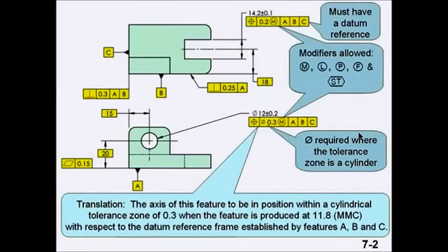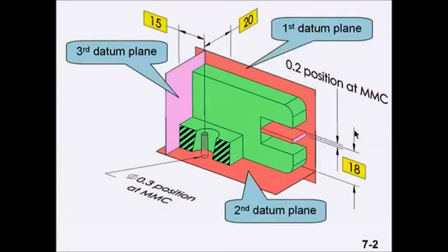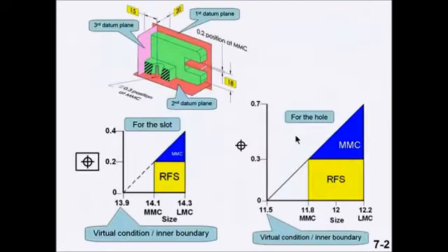Discuss the two position tolerances. Point out that when maximum material condition or least material condition is applied, there are two ways to look at the tolerance. One way, the traditional way, is to think about the tolerance zone controlling the axis or center plane of the feature.